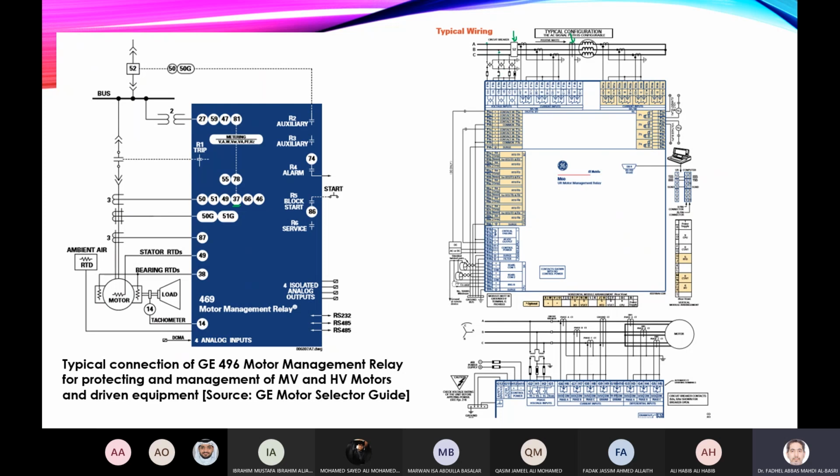And these are the three VTs, so it's connected as a star, and I need them sometimes to detect also under voltage or over voltage, or checking the sequence, if I lost a phase or not. Now, differential protection can also be implemented using this technique. I will come to this, that the two wires of each phase are passed through a CT. So this is another way of implementing differential protection for motors.